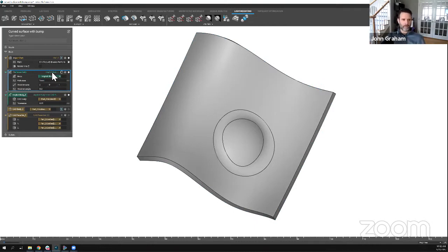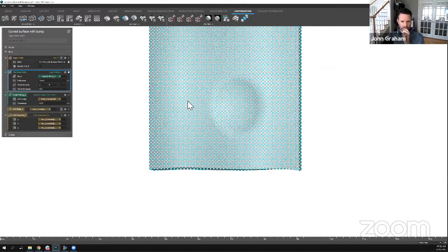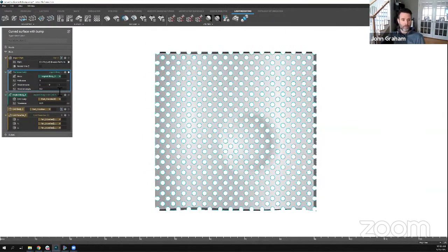It's this basic algorithm in nTop platform. We created a block right here I'm showing you that takes a given body and it just blasts it with holes, right? Because that might be what you want done relatively quickly. You see the parameters are exposed that you might need, right? And so again, we blast this with holes. I put a diameter in, and the spacing between them is basically fixed. And I've got minimal number of inputs in here, the hole size and the axis of rotation of how these holes are fitting next to each other.